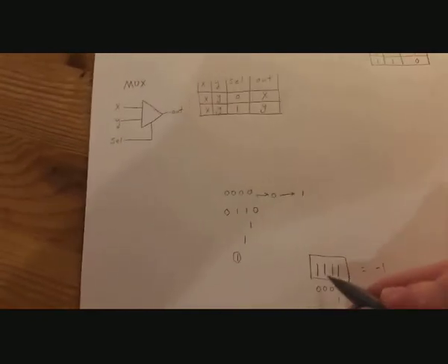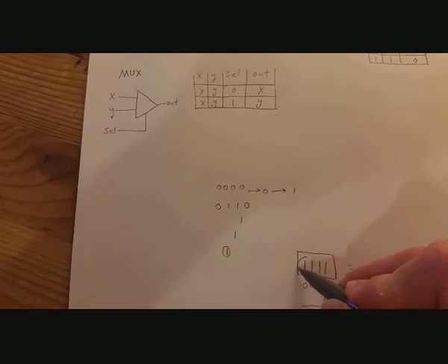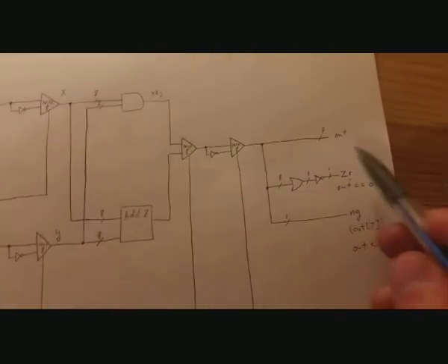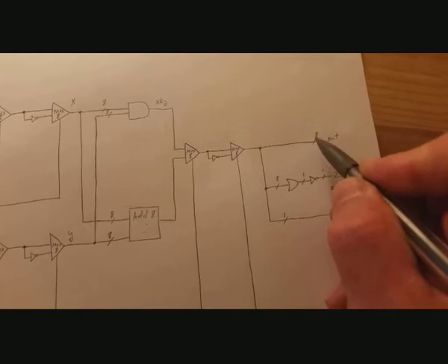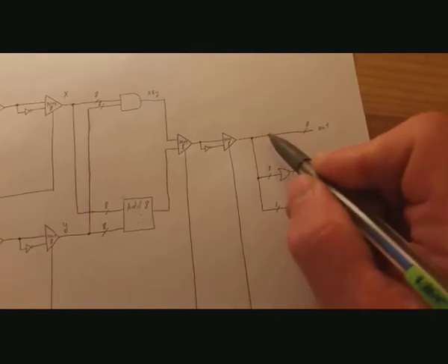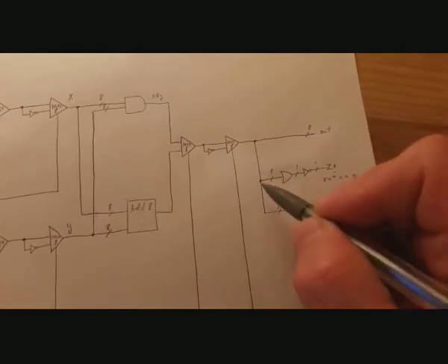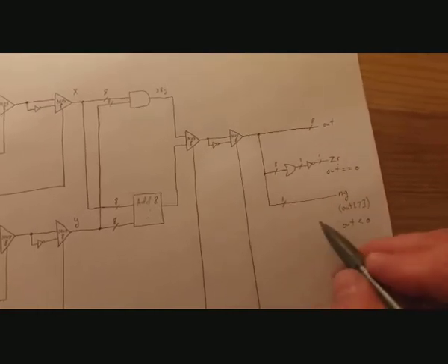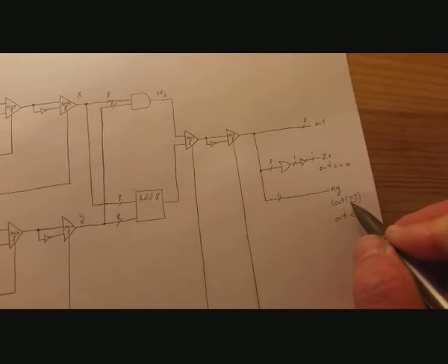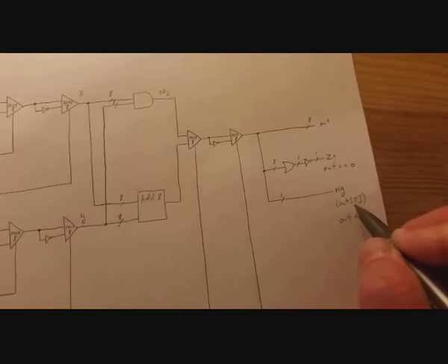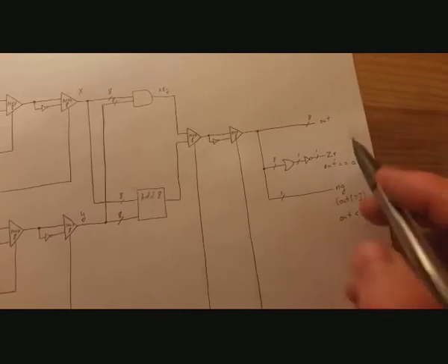So that's always going to be the case, no matter what you wind up with. This most significant bit is always going to be a 1 for a negative number. So what we're doing here is we're just going to take this most significant bit, the leftmost or topmost wire, and you can think of it like indexing an array, like the most significant bit of out.